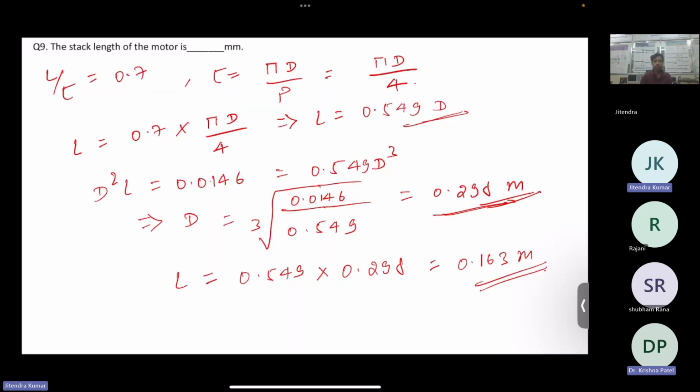Answer, there is a peripheral speed if it is given. I have one doubt about which equation we have to use. Say, for example, maximum flux density is given, so average we can find out. In that case, do we require a form factor? The number of poles is given, the rating is given, the speed is given, and we have to find the total air gap flux. So which equation correlates this peripheral speed?